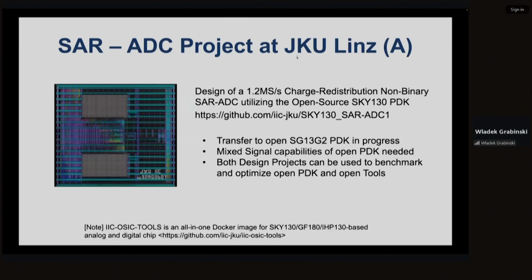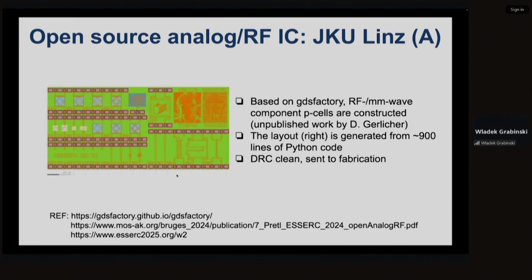I was already referring to our partners at the Technical University in Linz. They started using Skywater, but now they are porting all their designs into the IHP 130 nanometer BiCMOS process. They are also experts in analog RF design, and recently submitted a full analog RF test chip for RF microwave applications.